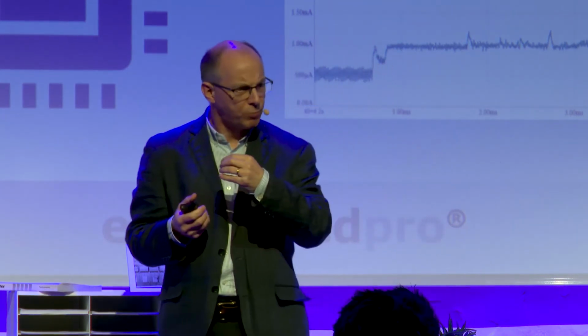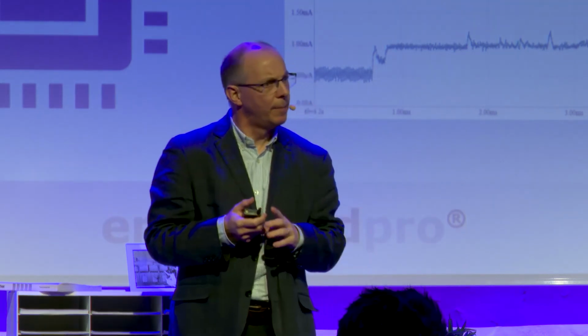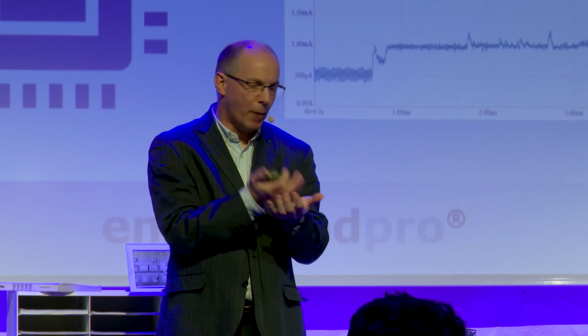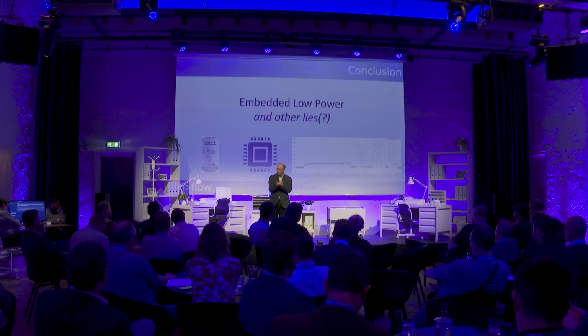Now we need some probably analog design to design the kind of circuit that's going to help us wake up on the sensor, but take zero current. That's not always easy with some sensors. A gyroscope, a micro machine kind of gyroscope, is going to take more current than you could possibly want to have awake all the time. We were talking about this last night.